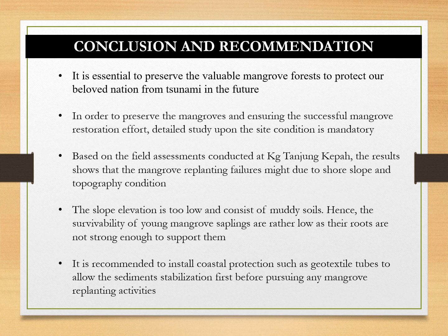It is recommended to install coastal protection such as geotextile tubes to allow sediment stabilization first before pursuing any mangrove replanting activities.